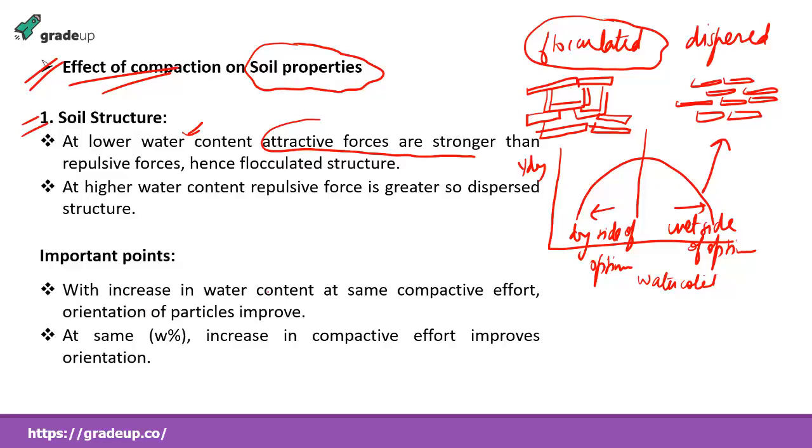With increase in water content at same compactive effort, orientation of particles improves. Okay, and at same water content, increase in compactive effort improves orientation. Let's see this.